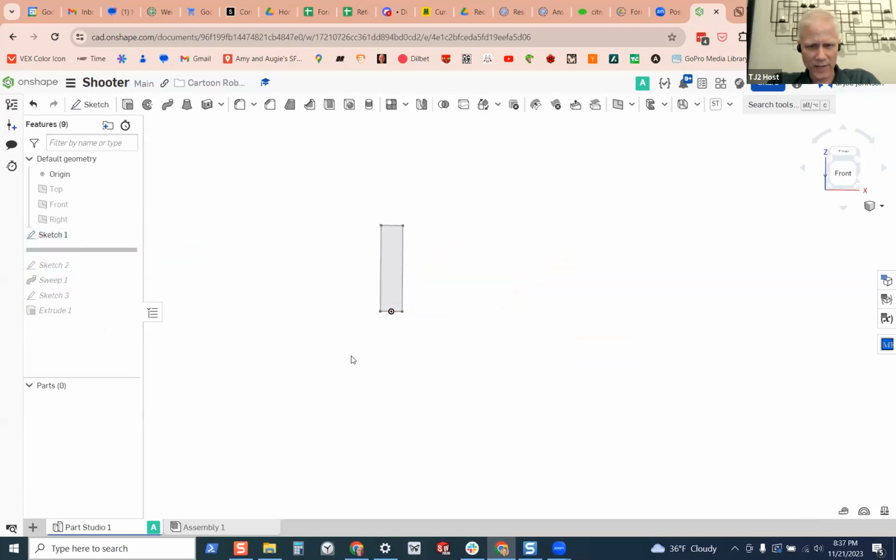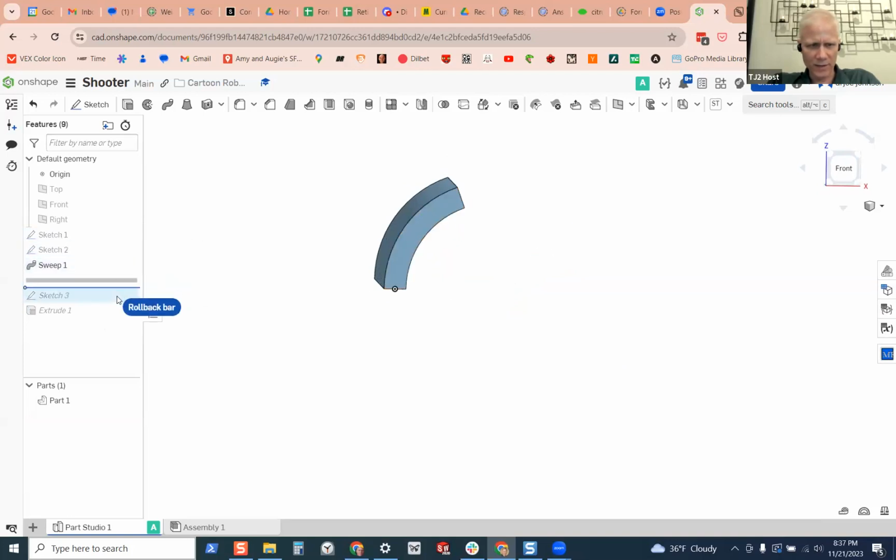So you made a sketch, then you made another sketch, and then you swept that sketch to make your thing. Perfectly good. Now, then you did another one to make your circle, but you didn't put your circle at the center of this.